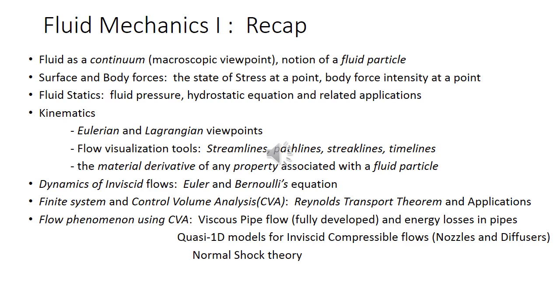The first and foremost thing regarding any continuum mechanics course is the fundamental idea of treating the medium as a continuum. So fluid is a continuum, and what we mean by continuum is that we disregard its discrete nature, because we know that all matter is discrete eventually at the atomic and molecular level. So the processes at the atomic molecular level are basically disregarded in a continuum treatment. Rather, we treat it as a continuous distribution of matter.